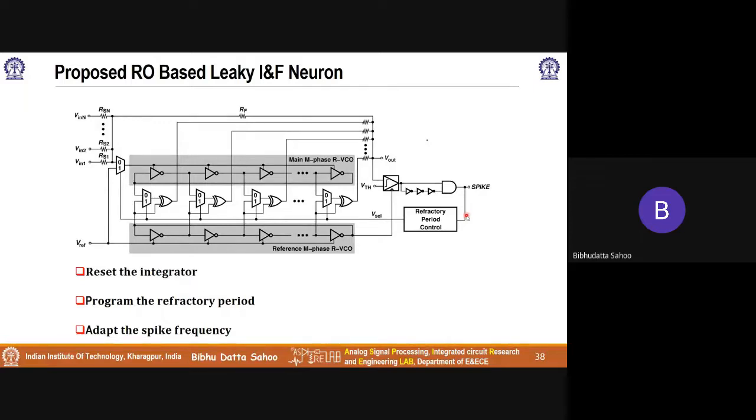You will be training them, and those training values will come from a simple resistor ladder resistive DAC, because we are not operating at very high frequency. There are some training things. We'll show how the training coefficients will be programmed onto digital D flip-flops and control the DACs and adjust the training, the spike frequency and the refractory period.